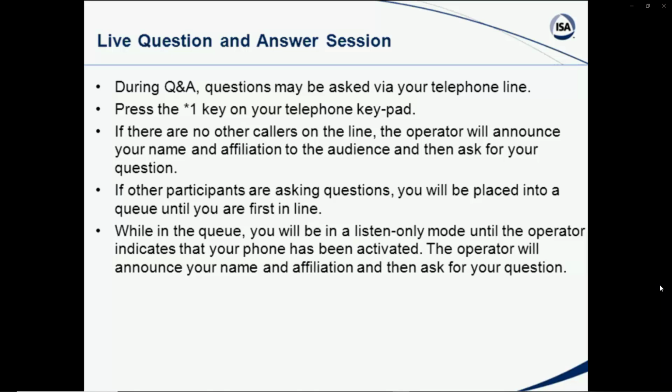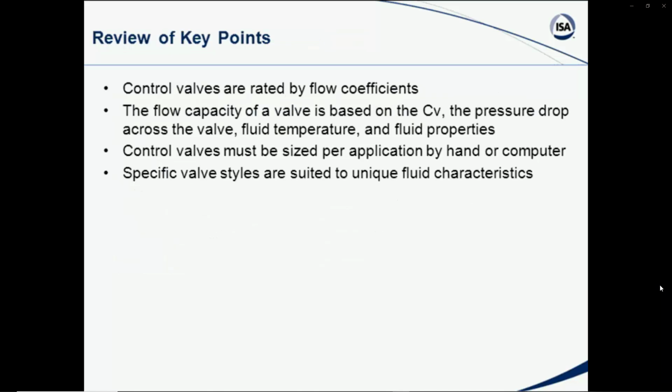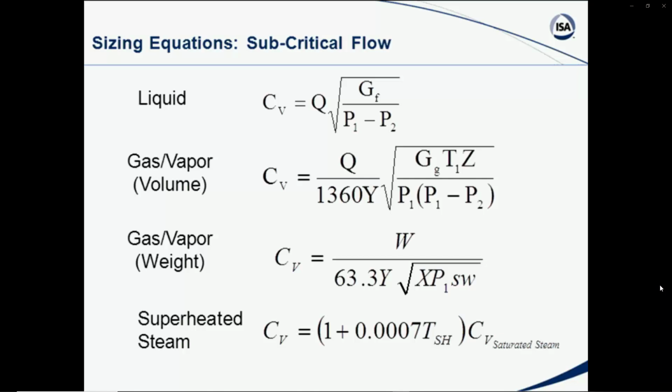Yeah, I just wanted to confirm, you had talked about the temperatures being in degrees Rankine. I just wanted to verify, because the valve sizing for steam talks about the superheat being degrees Fahrenheit above the saturation temperature. Yes, it was still that particular correction, and I was moving back to there. That particular correction is in degrees F. You will have the degrees Rankine used in the equation, and you would get a C sub V value for that. But then you would need to correct based on the degrees Fahrenheit above the saturation temperature. That's correct.